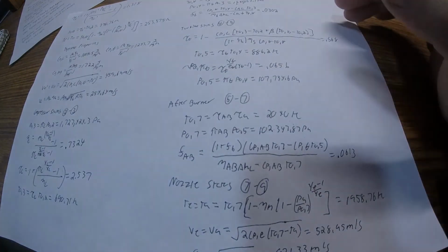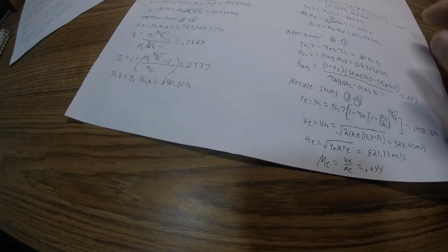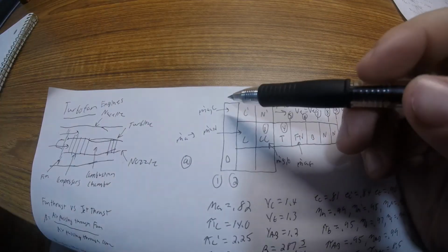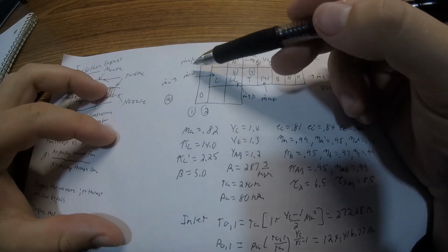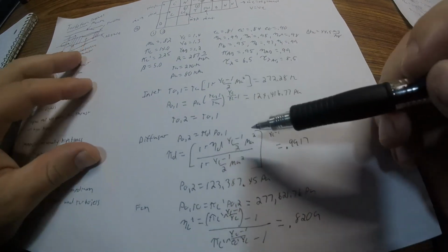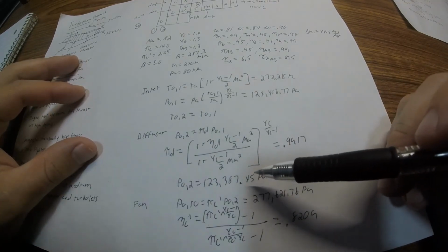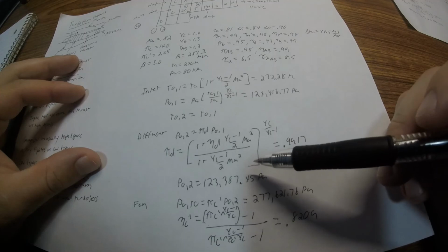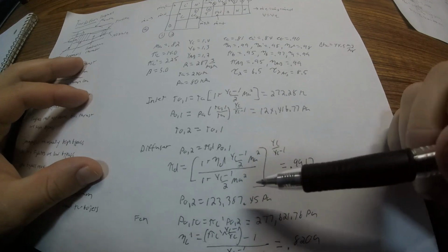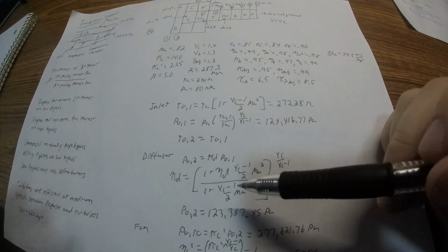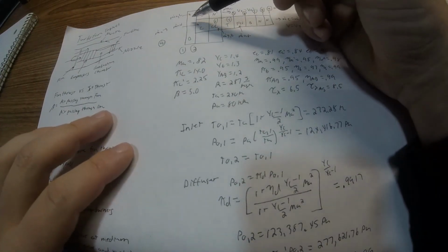But what I really wanted you to see is that going through these calculations is good because you can see how the pressure and temperature are affected at each state of our process. So we can review it one more time. As the air is coming through from the atmosphere, pressure increases to state 1, temperature increases. As it goes through the diffuser, the pressure drops, but temperature stays the same. The pressure drops just a little as it goes through the diffuser.